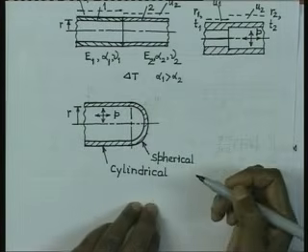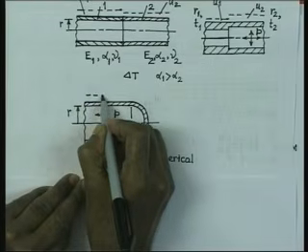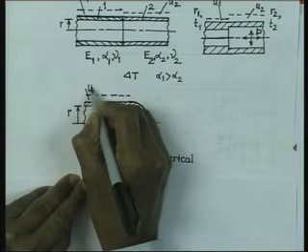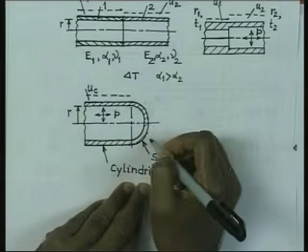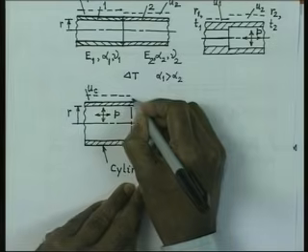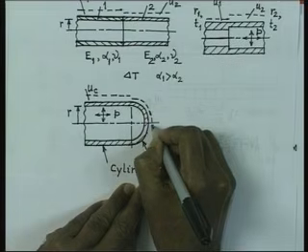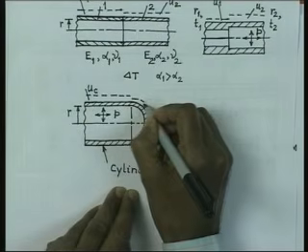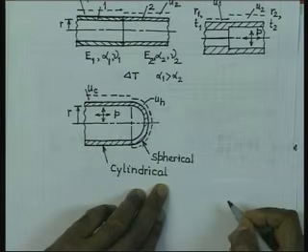And if you now consider the thickness to be the same, then this cylindrical portion is going to have expansion under the action of the internal pressure. Let us say that UC is the radial expansion, and similarly the head portion, or the spherical portion, is going to expand also radially, and this radial expansion is, let us say, equal to UH. It can be very easily obtained